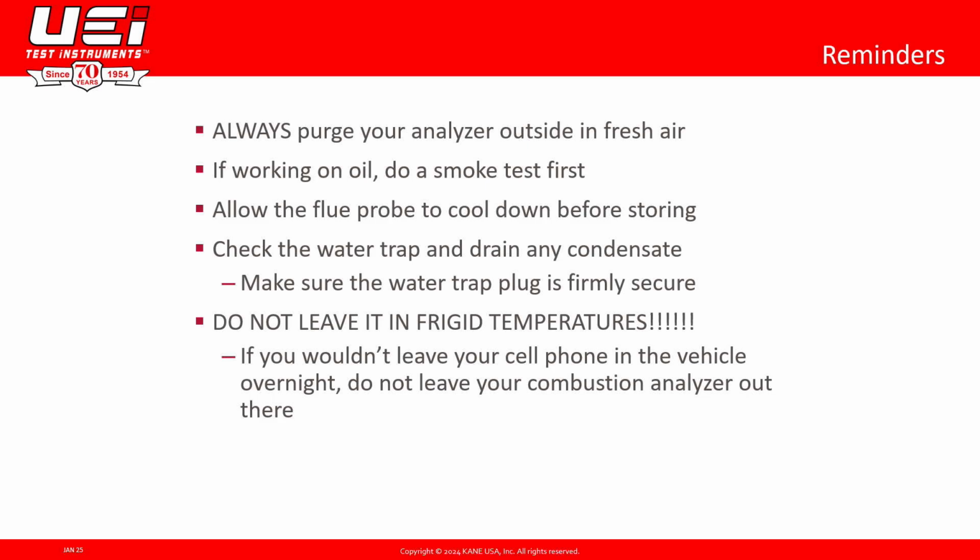So one of them is always make sure that we're purging it outside in the fresh air. If you happen to be working on an oil unit, and by the way, we do also offer oil kits so you can get the smoke pump with your combustion analyzer as well, we want to make sure that we're doing that smoke pump test first, because oil can be dirty and it can be nasty and it can gum up your analyzer pretty quickly. So it's important to do that smoke pump test first.